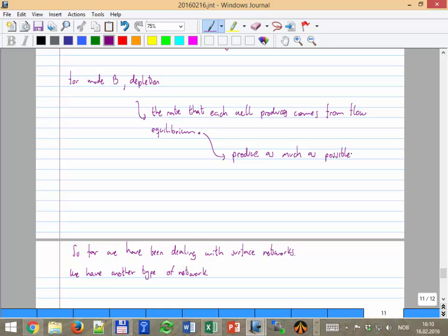So I want to put things like a multi-phase booster, a compressor, maybe a bigger pipe, or add more wells to the system, so it will produce more at that given stage, to increase its potential. But also something else that we didn't consider is that the associated products like the gas, GOR, and water cut increase with time, and can overload the processing facilities.